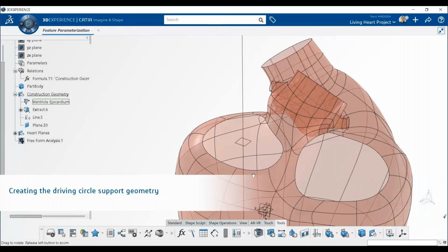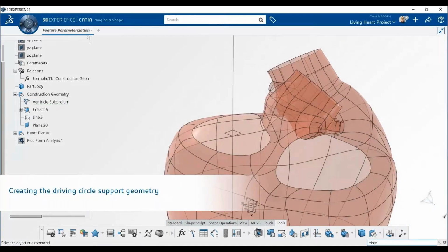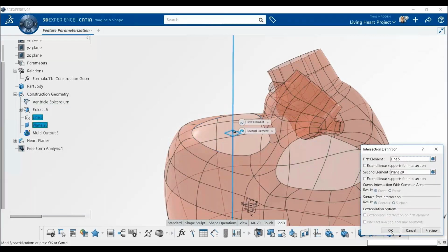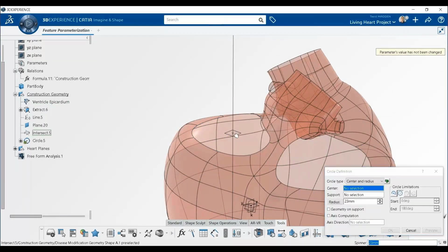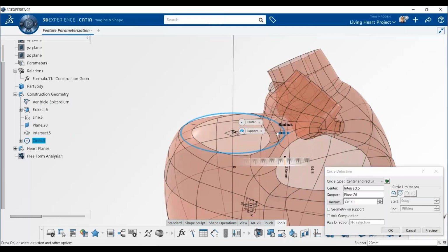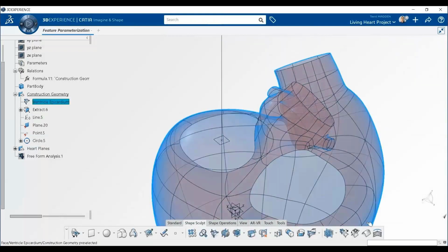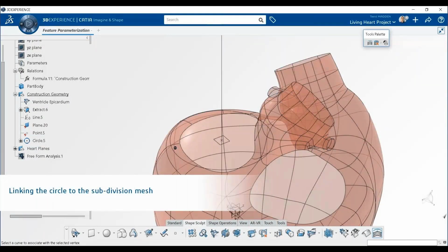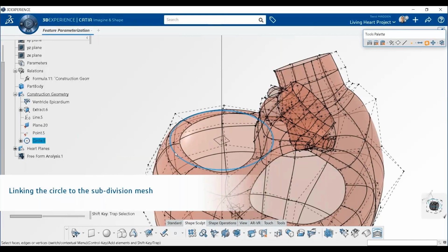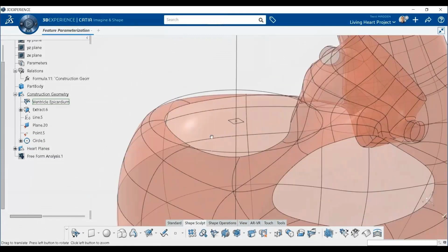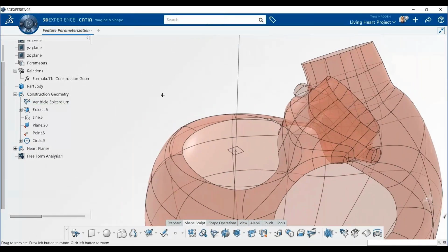That's going to be tied to the model, right? So we have a direction, an outlet direction of our mitral valve that we're looking to scale, a radial value in, right? So I have my radius value that I can easily adjust parametrically, and basically what this will allow us to do is centrally scale just those nodes that we want to tie to this wireframe surface to that radius value. So there you can see all those nodes just at the top annulus opening are going to be tied to this radial value.